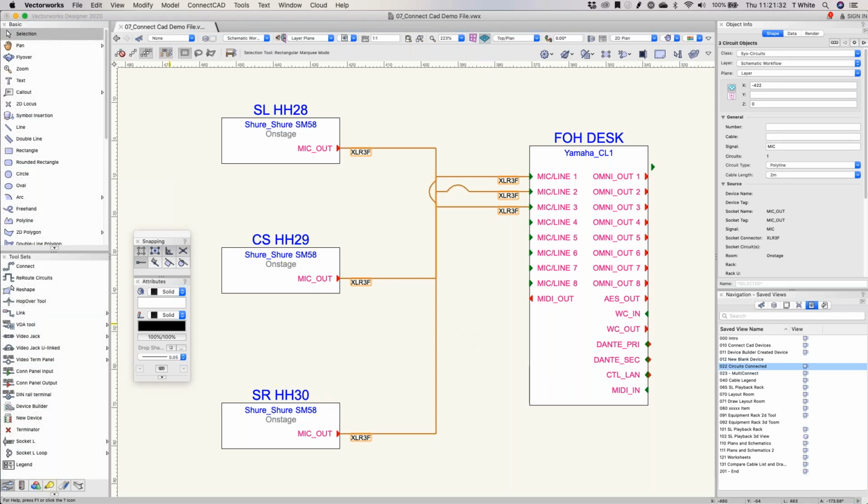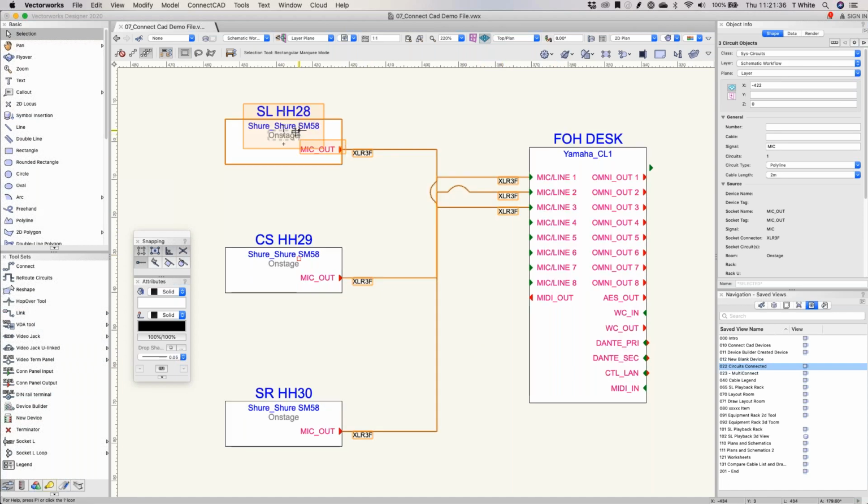Okay. Other tools in here are where you want to place things. Most of my work just involves ConnectCAD devices. If you want to look at things such as tie lines or BNC, or any particular patch panel elements, or even DIN rail connections from electrical circuitry, RCD protection, etc., you can place customized panel mounted connections straight onto the document as well. And there's obviously a terminator if you want it, and you can loop in and out of a particular device should you want to display that.